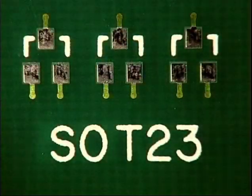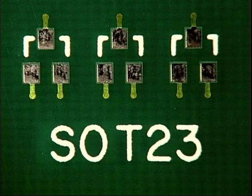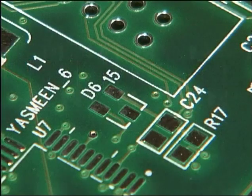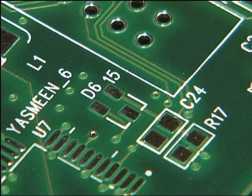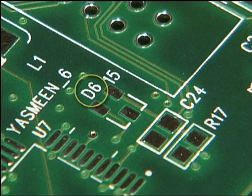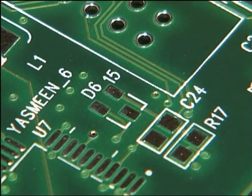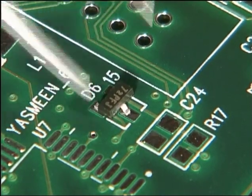SOTs come in different sizes. The most popular SOT is the SOT23. As with any transistor or diode, the reference designator is Q for transistors and D or CR for diodes. Orientation of SOTs is determined by the lead and land patterns. There is only one way to place the component.